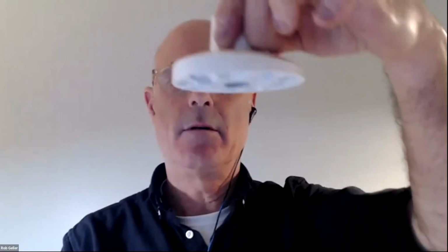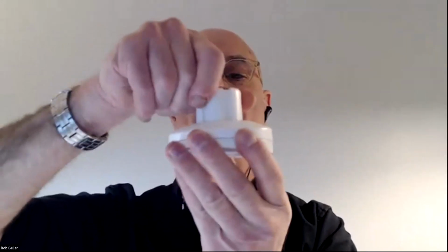And you can see that it's cut a bit on the diagonal, both halves. And as you rotate it, I'll try to rotate it, you can see that it offsets the angle. So you can attach it afterwards on the surface of the concrete without having to shim. You just dial it in.